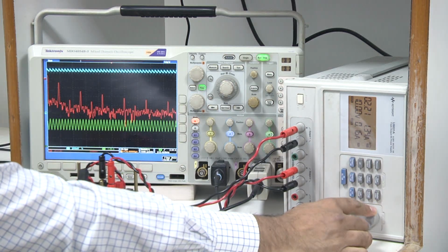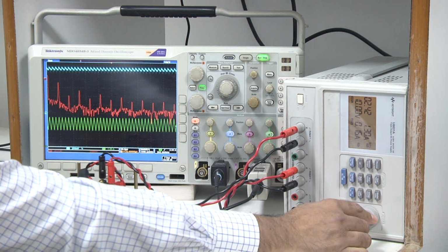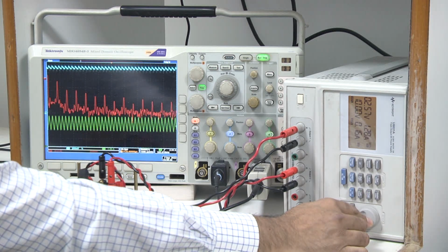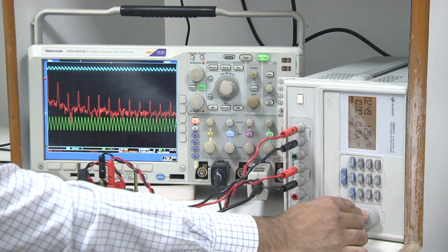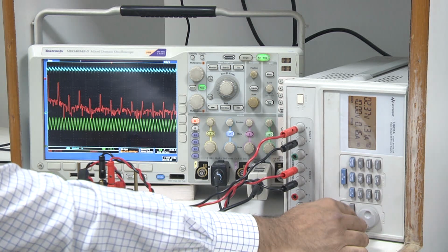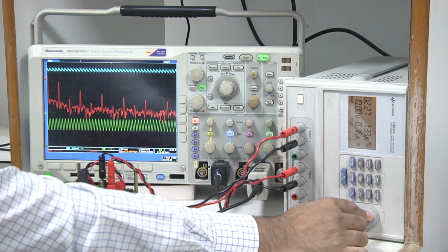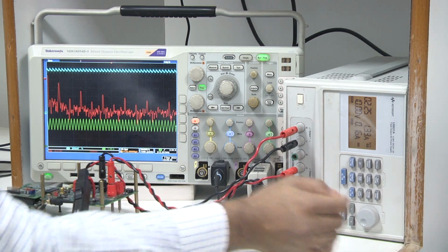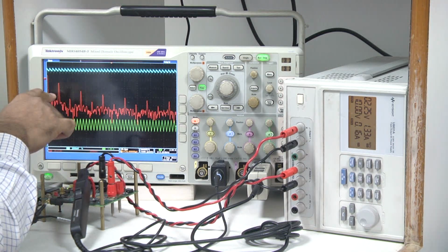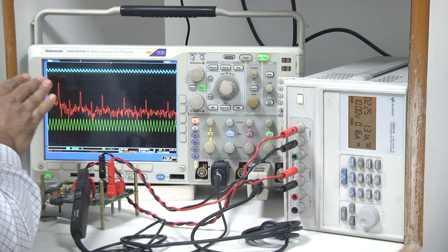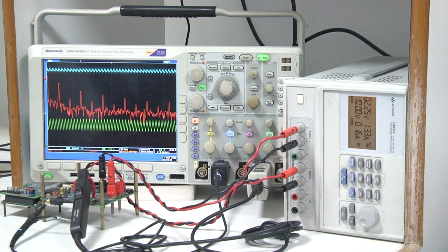That means if I show the process of movement, 2.5 to... slowly that peak is shifting. So you can see the peak is shifting. This is 2.5, and this 2.5, the peak is now coming in between 200 to 250 kilohertz. So maybe it is around 210 kilohertz or so, but it is perfectly stable because the duty is quite large. And another point you will see, the ripple has got reduced.